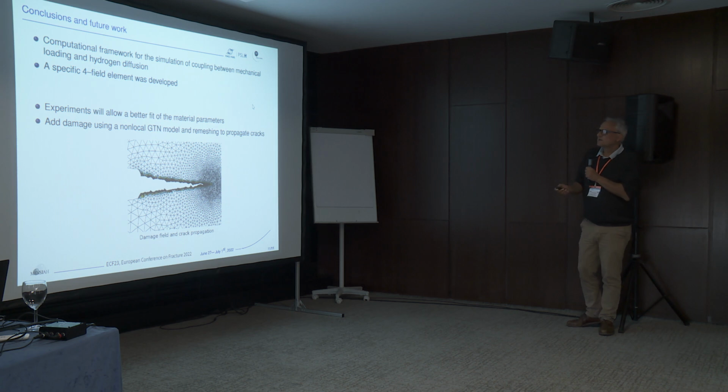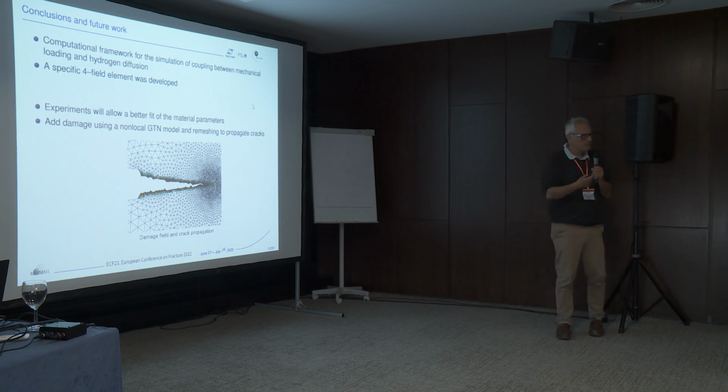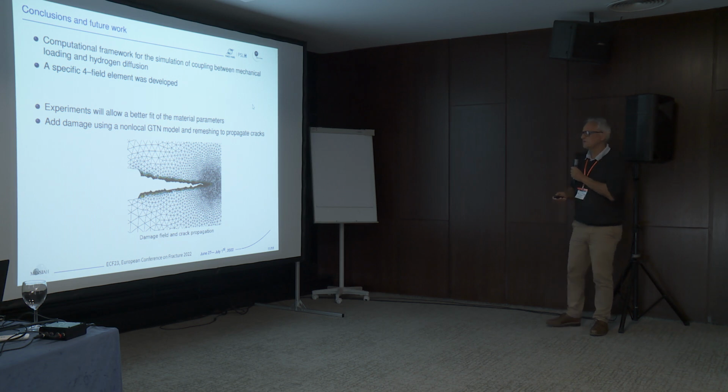Okay, so what I've presented is a computational framework for a strong coupling between mechanical loading and hydrogen diffusion. We have developed a specific four-field element. And very soon we'll have the experiment, so we'll be able to better fit the material coefficients. And indeed, I expect the material to break with damage, so we are going to link that with a non-local Gurson model, void growth and so on, and be able to propagate cracks with remeshing and mixing all together.